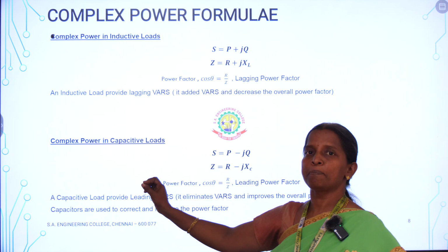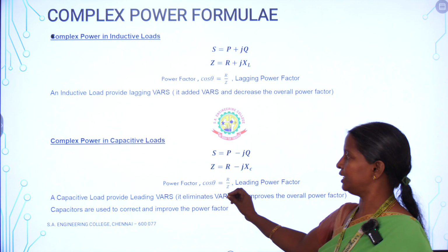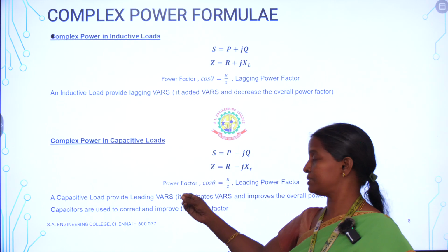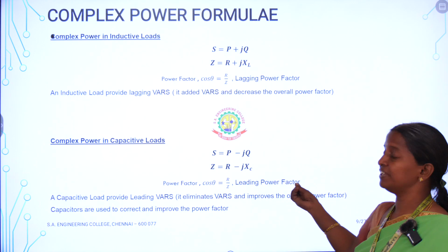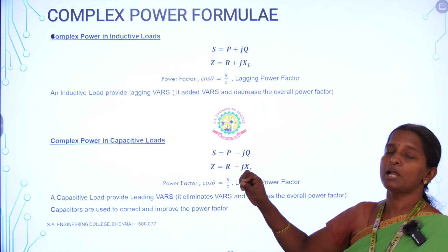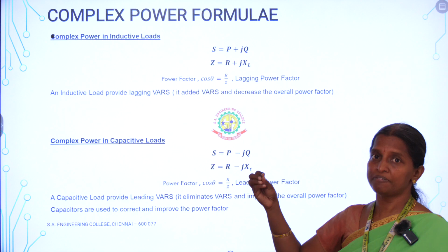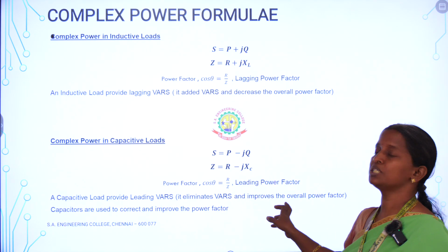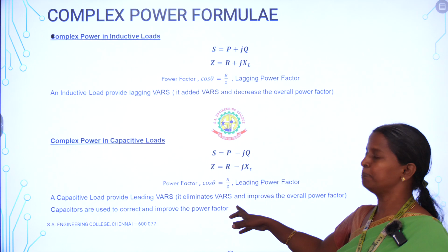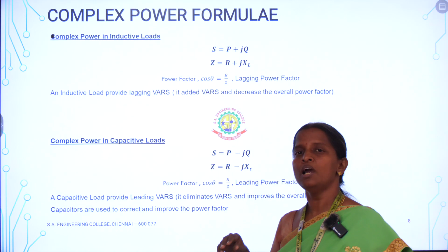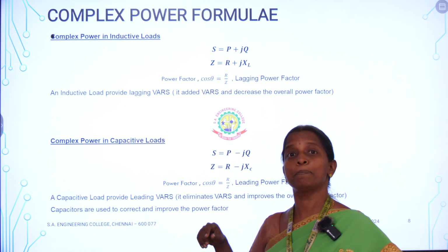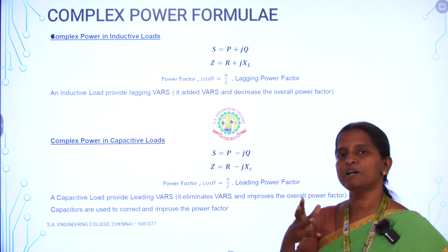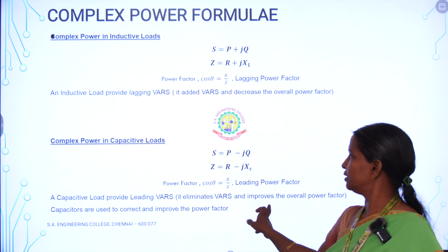And also the capacitive load will provide the leading VAR, that is voltage ampere reactive. That is, it will improve the overall power factor. So the overall performance of the power system will be improved if you are adding the capacitor in the circuits. So this is a very important thing, so that only we will use at the receiving end, we will use the capacitor banks. It will improve the power factor and it will improve the overall performance of the power system.